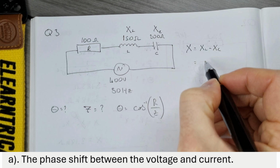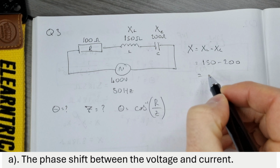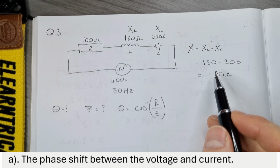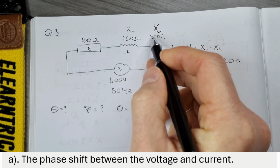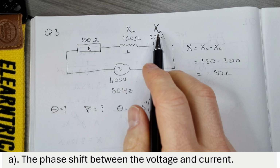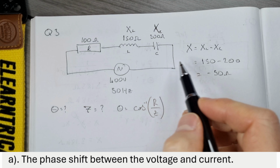So it's going to be 150 minus 200, and that gives us minus 50 ohms of reactance. Now the negative here tells us that the capacitive reactance is greater than the inductive reactance, and as a result this is going to be a leading circuit, which means that the current is going to be leading the voltage.